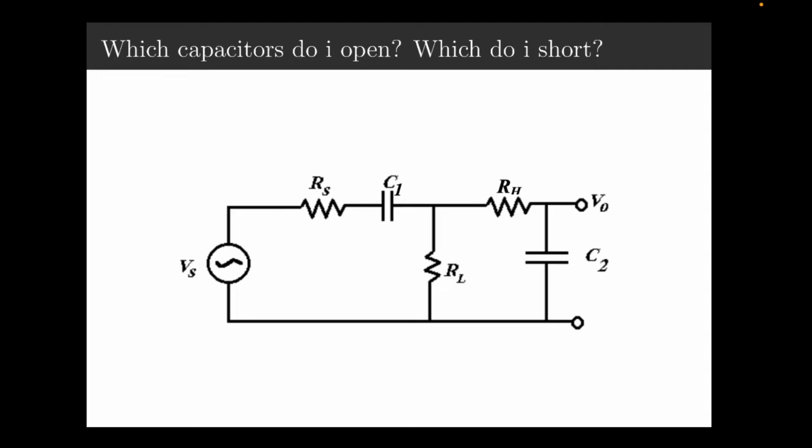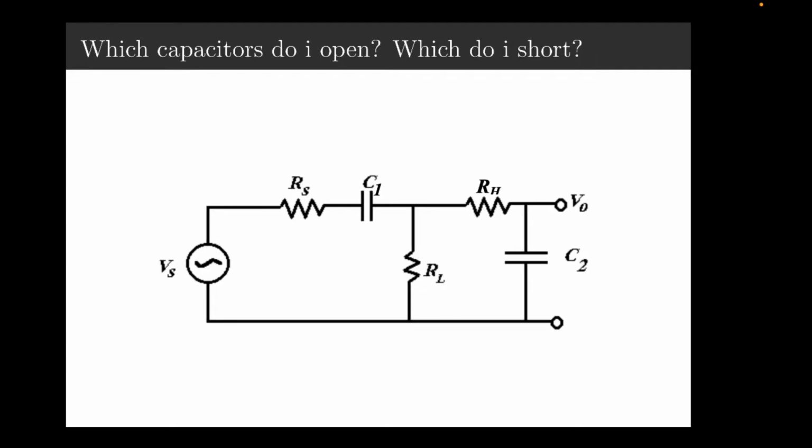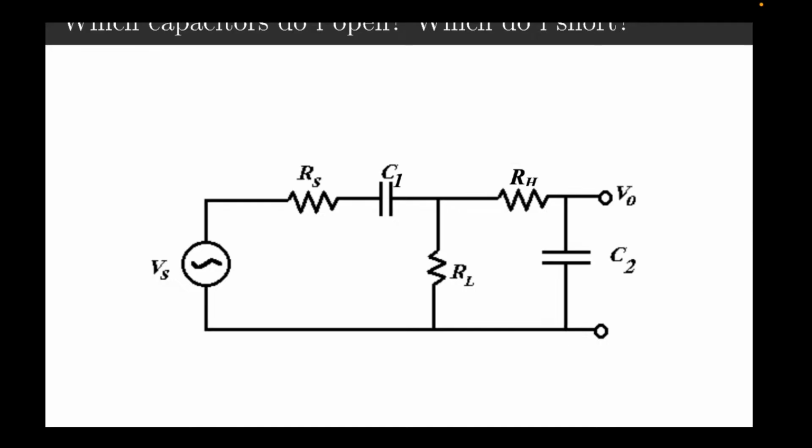It's a high pass connected to low pass. That's a good way to think about it. One way you could really find this is just doing casework. It's basically what you said. What you would do is that looking at these capacitors, you just consider low frequencies and high frequencies. So at low frequencies, what would happen is that these capacitors would be opened.